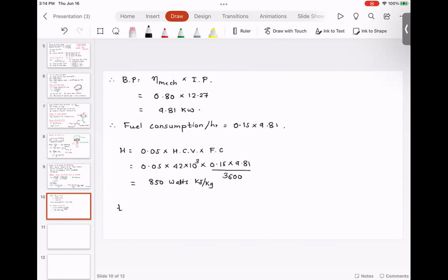Then from heat dissipation, TH is equal to H over 12.56 times K times (TC minus TE). And K for cast iron, please look at the textbook. It's 46.6 for cast iron.